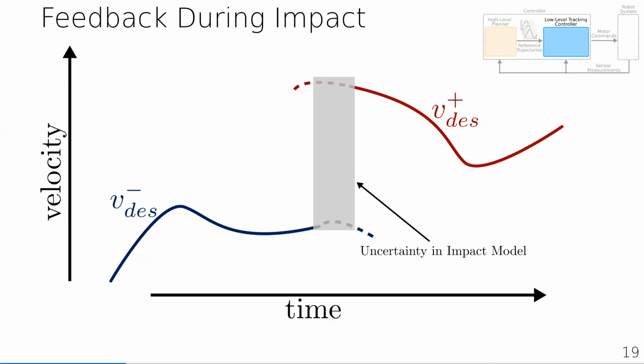What I'm getting at is that this problem is obviously super difficult because you want to control the timing of contact, pre and post contact. But could there be a way to alleviate that by thinking in phase space? You need to do this because you're tracking a time reference trajectory. But what if you're not tracking time? Could you track something else, like a phase space trajectory that's more state dependent? Then this problem would be less finicky, and you wouldn't need to control for those timings, right?